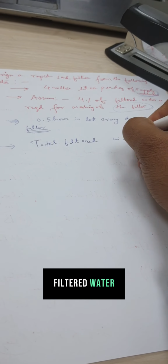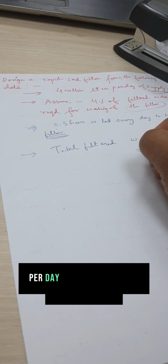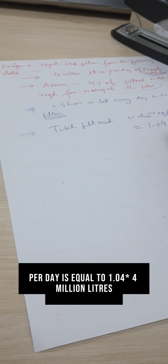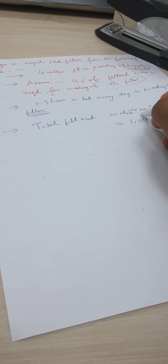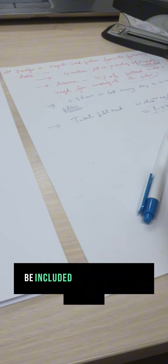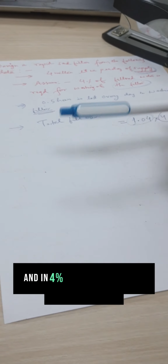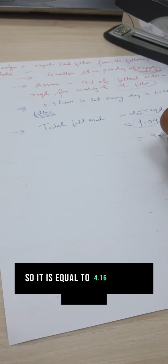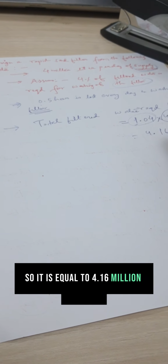So here the total filtered water required per day is equal to 1.04 into 4 million liters. If we are assuming that 1 liter is being treated and we are using 4% more, it's 1.04 into 4, which is equal to 4.16 million liters per day.